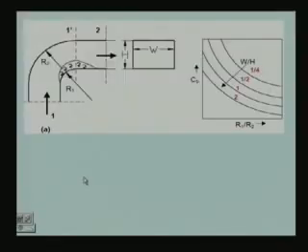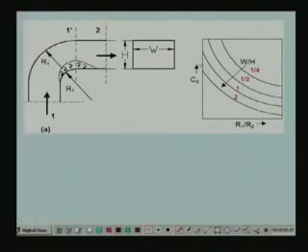So, as I said, this is your 90-degree bend, and here the dynamic loss coefficient Cb is plotted on the y-axis, and on the x-axis you have the radius ratio, that means the inner radius divided by the outer radius of the bend, for different aspect ratios. Aspect ratio means this W divided by H. So, what do you observe from this one?